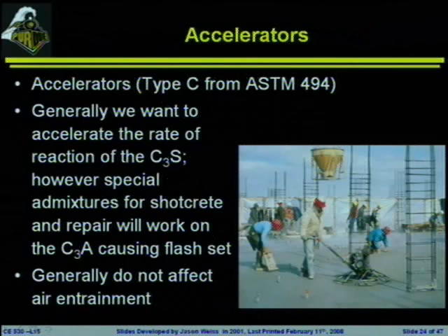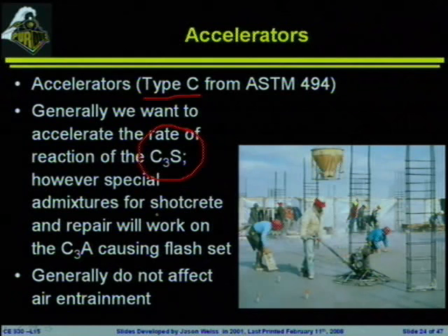So as mentioned, generally we're talking about type C accelerators. Generally these admixtures are related to the rate of reaction of the C3S. However, I will point out that in repair and in some of the shotcreting applications, shotcreting basically being like spraying a cement paste or a cement mortar up on a wall, they will work not necessarily on the C3S.